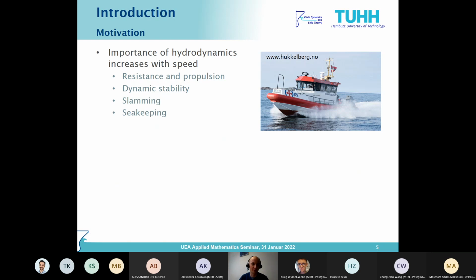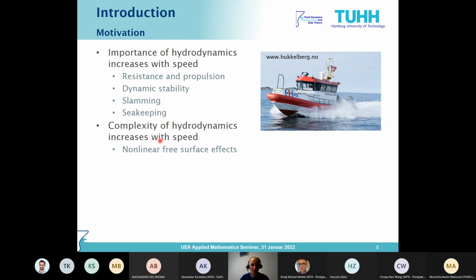They all become more important when the ship speed increases. At the same time, the complexity of hydrodynamics increases as well. As you can see from this picture, there's a jet developing, and there's a lot of spray. In general, there are a lot of nonlinear free surface effects, and there's also flow separation at the transom stern and at the chines.